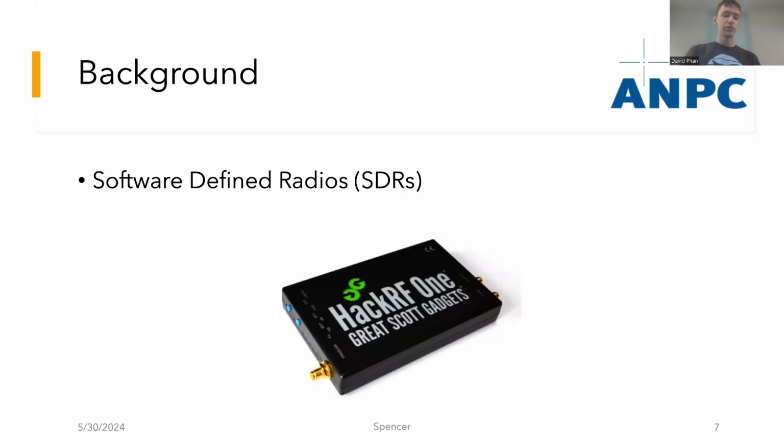For our SDR, we used the HackRF One, which is an open source hardware project for easily programmable transceivers. Being a transceiver allowed us to transmit and receive using the same two pieces of hardware, and it is easily programmable in GNU Radio, which allows us to control frequency, power, and filters. This made it simple to follow FCC guidelines and restrictions, and the antenna connection made it easy to swap out our antenna whenever we wanted.